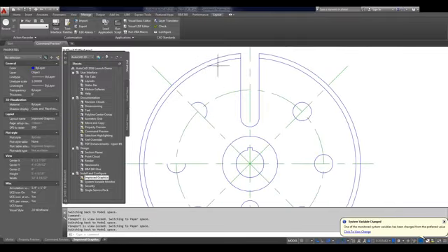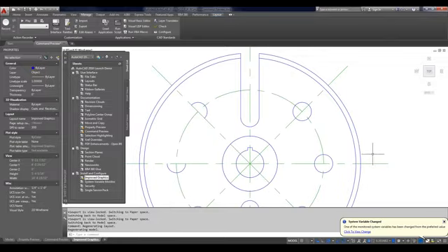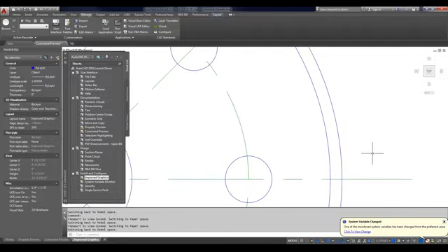All right, so notice the circle, that the curve is not very smooth. And that's because I have my new system variable, HQGeom, turned off. And again, I do need DirectX 11 for this to be enabled. I've right-clicked over the graphics performance utility, or 3D config command in some cases, and you'll see that I have DirectX 11 here. If I turn on this variable, which is on by default if you're running DirectX 11, you'll see a much smoother surface here.